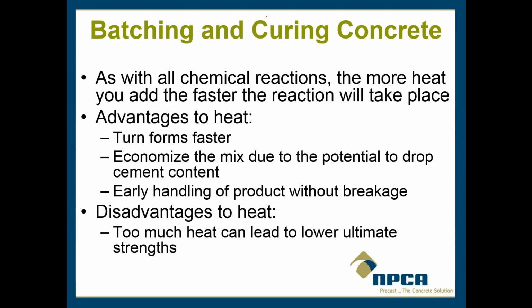So someone asked earlier about moist curing procedures and whether or not that affects your water to cement ratio. It does not affect your water to cement ratio. For example, if you're sprinkling the concrete, keeping it moist while it's curing, the water on the surface of your concrete is going to evaporate. When you add a little bit extra water while it's curing, that just keeps things moist. It prevents plastic shrinkage cracking, and it keeps the concrete at an ideal moisture to make sure that all the cement is hydrating, and that cracks aren't forming because tensile stresses aren't forming, because there's enough water to hydrate everything.